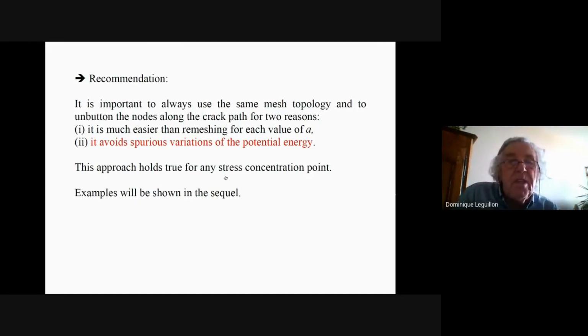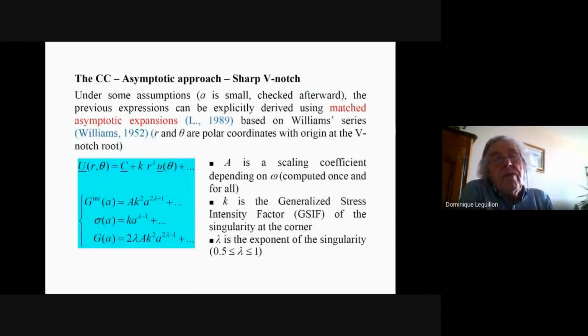Many tests have been done in 2D and in 3D. It's interesting, and it works for any stress concentration point. If it is a sharp V notch, it works, but if it is not a V notch, but simply a circular cavity or something like that, there is no singularity, stress is not increasing to infinity, but you can use this approach.